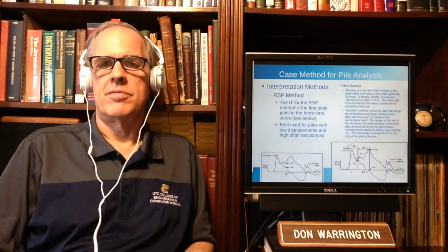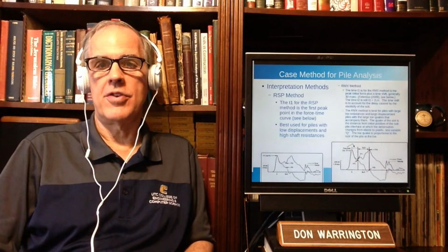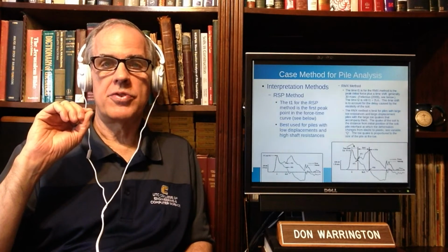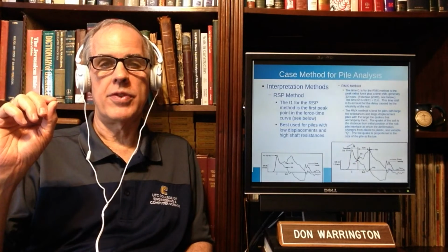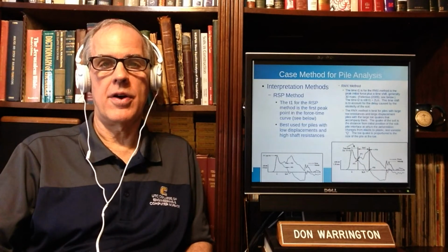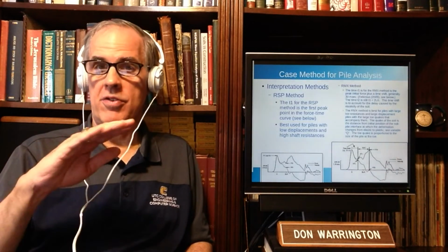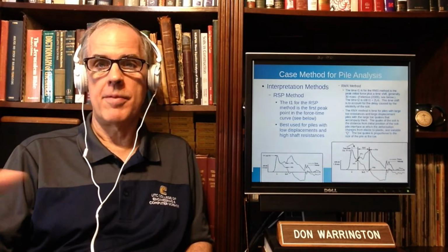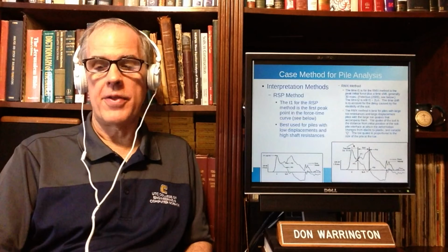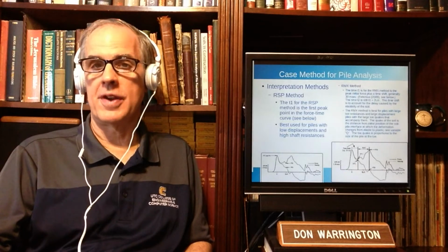Interpretation methods. Just like static load testing, dynamic load testing has interpretation issues. First, let me get this out of the way while I'm thinking about it. In CAPWAP, once they've got the pile modeled, they run a static load test on the model. And they interpret that according to the Davisson method. They could just interpret according to another one. There are two methods that we're going to talk about for interpretation. CAPWAP aside, the case method has its own interpretation methods.